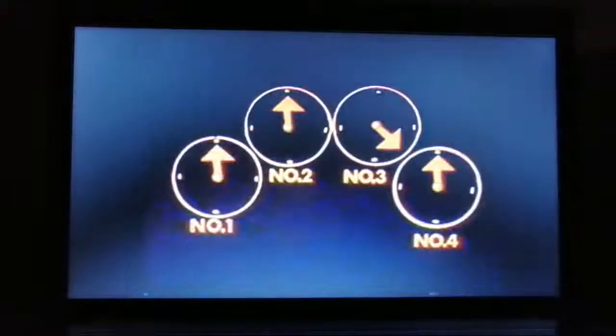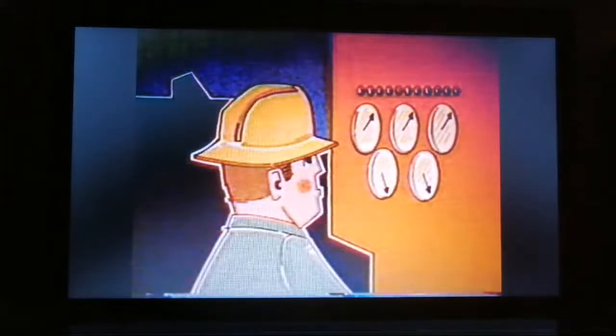If an instrument or analyzer does not seem to be correct, be sure the trouble's in the instrument and not in the system itself. The operator should use his instruments and not permit the instruments to run the plant. He can think and make decisions. Instruments can only help.